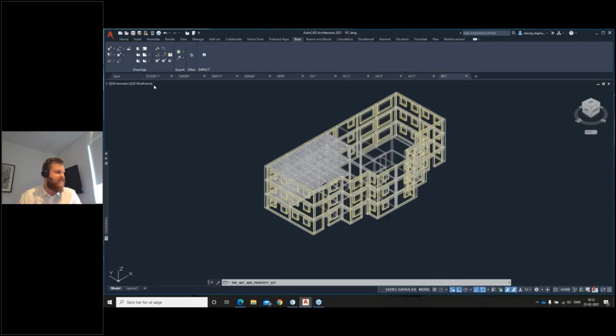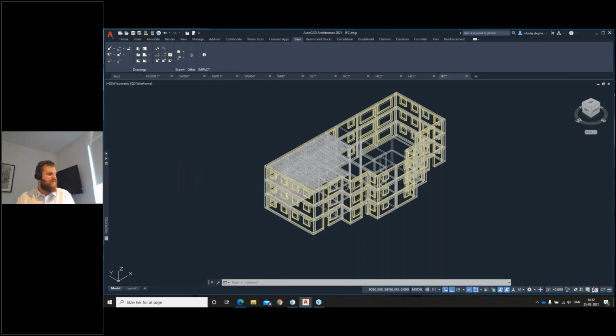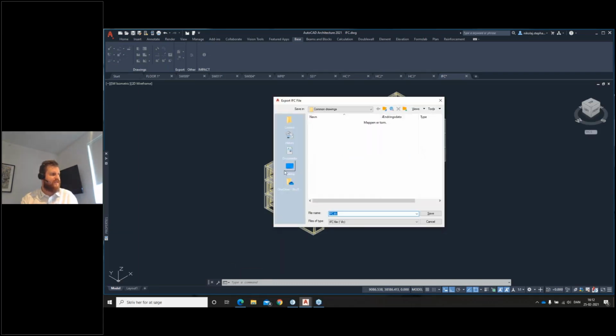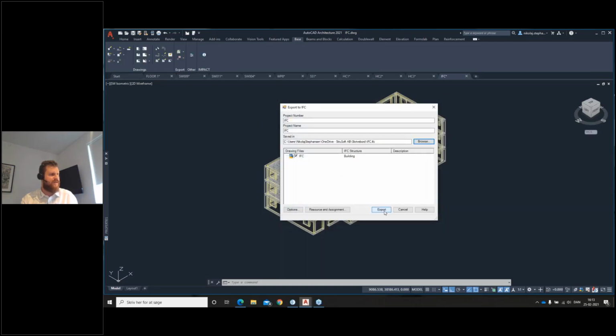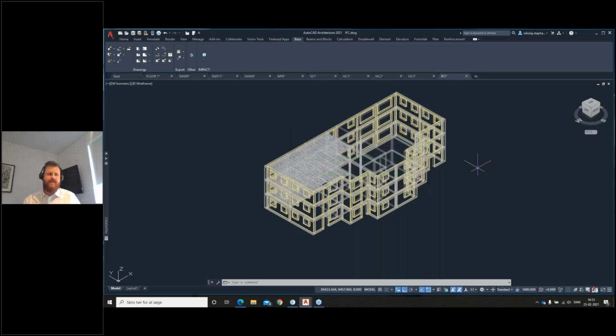I'll just take the standard in this one, just add that standard property set with basically, I think, half of the information available. I haven't planned anything yet anyways. Then I will export this into an actual IFC file here. We just call this project IFC, and we call the file IFC as well. I'll just put it on my desktop so it's easier for us. Click Save, click Export. Before, we had the Impact software generate the elements for us. Now we're putting them out into an IFC file.